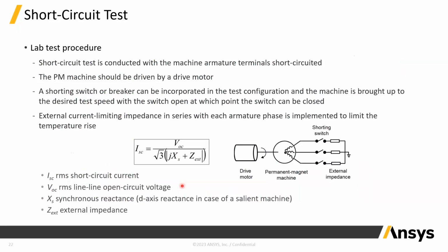The same type of comment relates to the short circuit test, because the short circuit test is a little bit more complex, and defining the proper setup where the electrical machine is driven and is measured against this short circuit, defining the relationships between the quantities measured in the test, and calculating all these parameters related to the short circuit, like RMS short circuit current, RMS line open circuit voltage, synchronous reactance, external impedance, and so on and so forth.